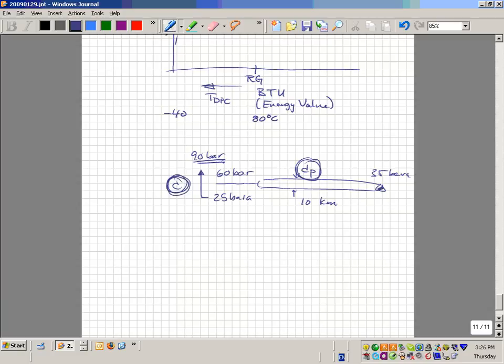That's in fact one of the most interesting things in the gas export system in Norway, because the higher pressure you have in the pipeline, you need more power to compress it, and you have more back pressure, but then you have more capacity in the pipeline for fluctuation in the user. In fact, in the Norwegian gas system, just in the pipeline itself, there may be 2 weeks export capacity. So basically they can shut down the field for 2 weeks before they're empty.